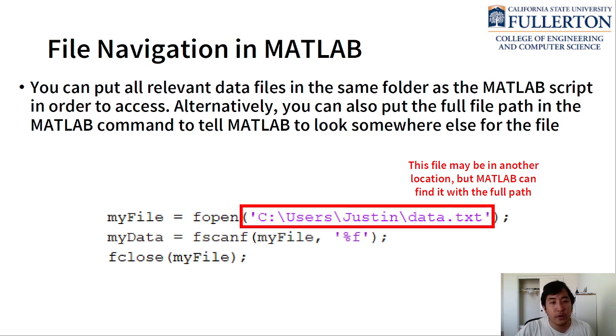Another way that you can do this, so let's say that you have the file in another part of your computer, is that you can give MATLAB the direct path to that file, right? And so if, let's say, this data file is located in this folder here, which is different than your MATLAB script, you can feed it that direct path, and then MATLAB is smart enough to go looking for that path instead of looking in the current folder. Okay.